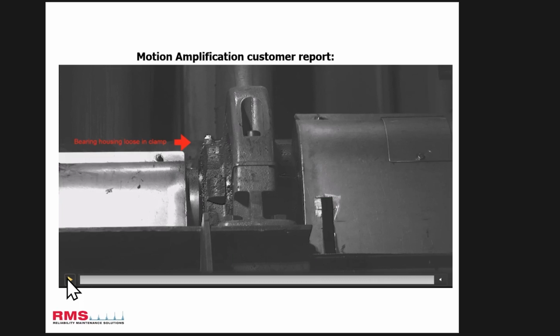So in some instances, that base plate there could be just moving and twisting a little bit, and we'd probably have to magnify it so we can make it visible. So people say, well, you can make it look worse than what it is, but ultimately we'd put an ROI on there and we'd have a vibration signature anyway. So you are in control of the magnification of the video up to 100%.